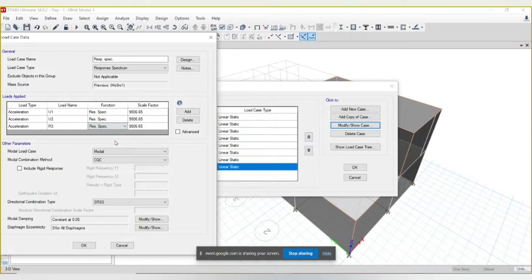the response spectrum. Now you have got all the possible modes of vibration in x direction and in y direction, rotation. And the modal case will be, this is the model which we have already made. Quadratic combinations, you are having different types of combinations, so you can use that. So as of now I will discuss quadratic combination.